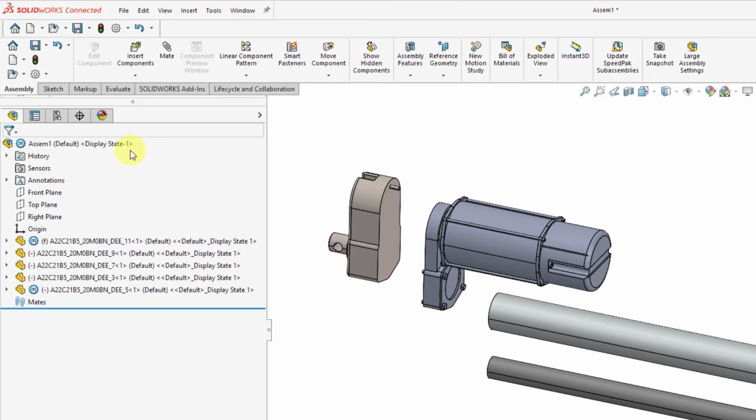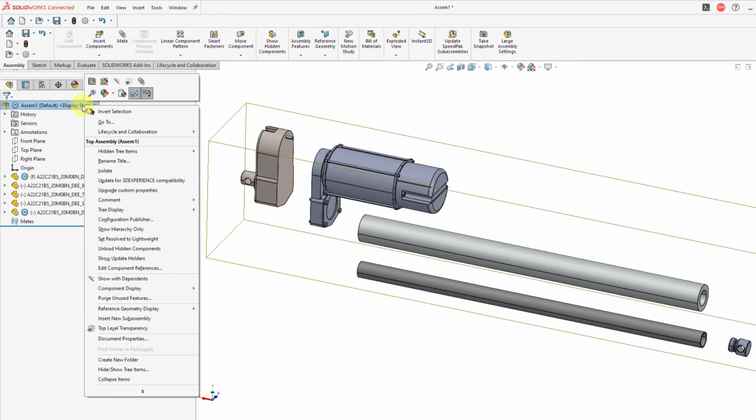The way that you do that is by right-clicking on the top node in the tree, and you're going to get a right mouse button menu, just like you get in Creo Parametric. You want to go down to the control for tree display. And there's a flyout, there's a bunch of different choices. You can see that some options are turned on, like show feature names, show comment indicator, and view features. But for what we want to do, let's go to component name and description.